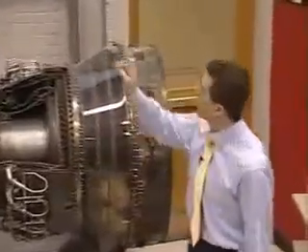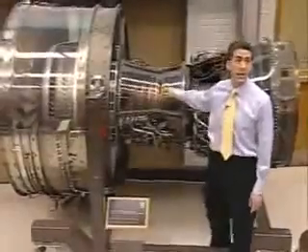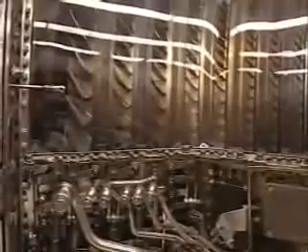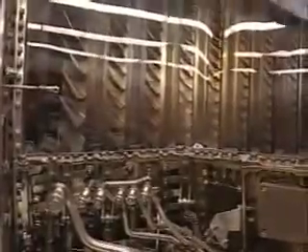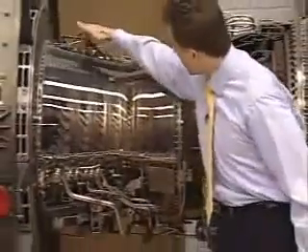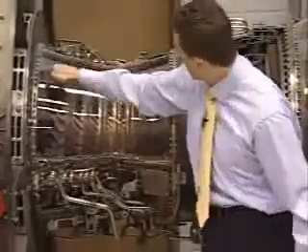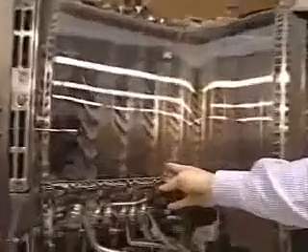And I just want to point out in this picture up here, and when you look at this engine, the various things that you're looking at. So this engine, when it spins, you see the rotating blades, right? These are called rotors. So those are labeled with R's on that diagram. Now what you don't see, because they've been cut away and pulled off of this, are that between each one of those rotating blades, and if you look up in here, if you've got the right view, you can see it, or if you look over here, you can see them. In between each one of those rotating blades is a stationary set of blades called stators.